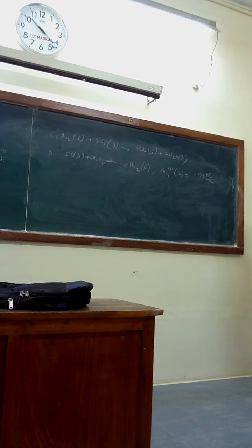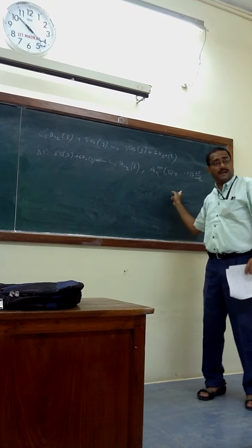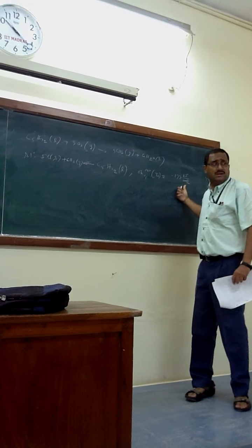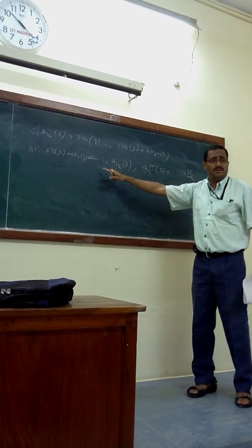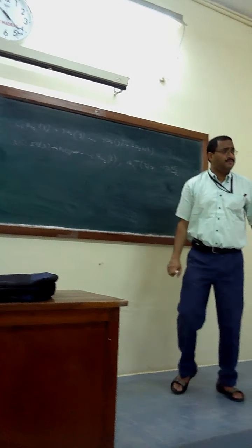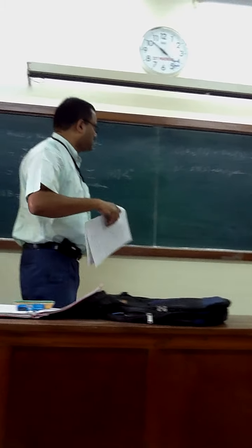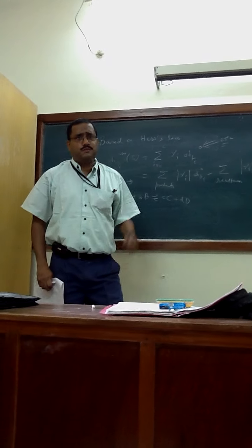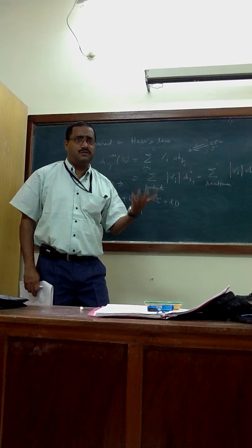This could be per mole of C5H12. Again, I am saying this unit is very controversial. You cannot say per mole of carbon, per mole of hydrogen, or per mole of C5H12. Okay. No books address that. When I was teaching process calculations, I was stating this. This per mole is very important. Generally, we don't care; we do the calculation, solve, and move on.